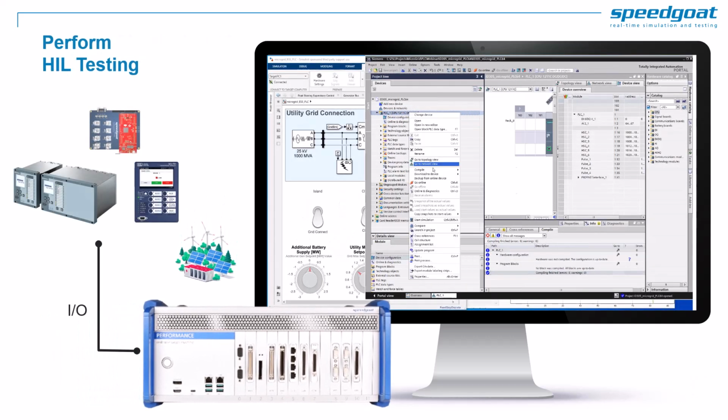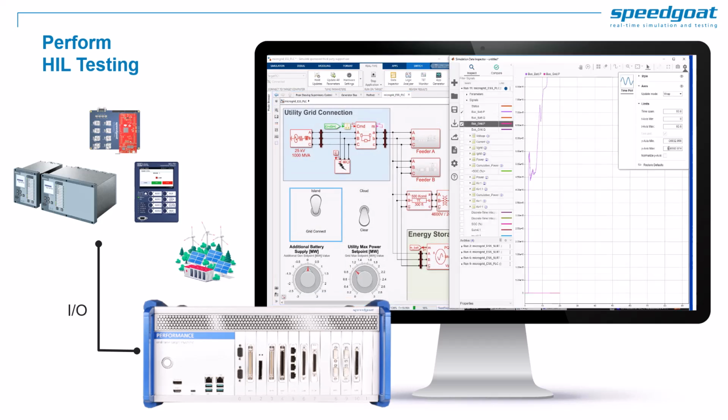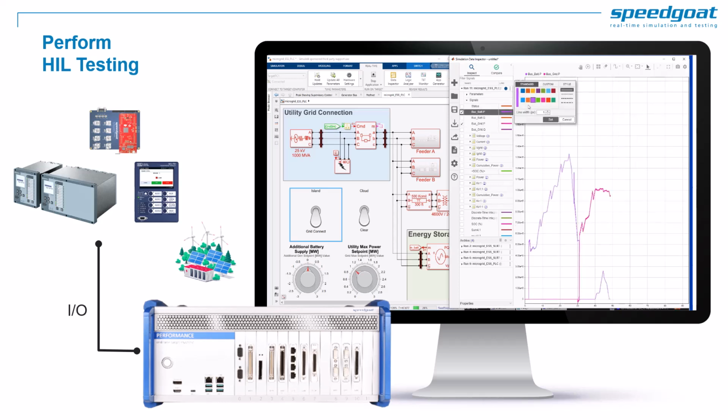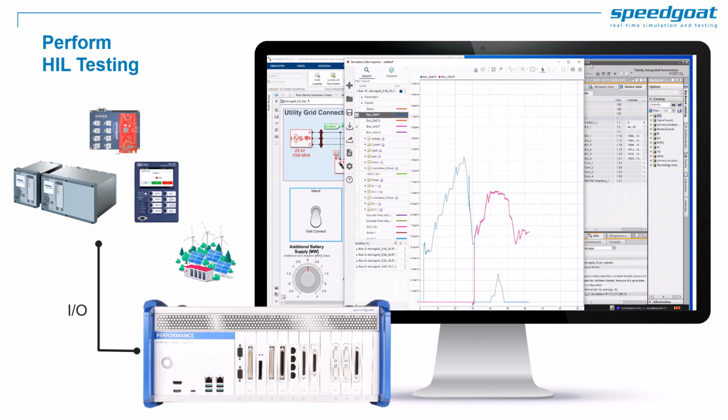Now you have your plant model, which represents your real system. And from the I/O level or communication protocol level, they are running in real time and they behave just like your real plant. The difference is that your plant model is virtual. So when you hook up your controller to the target machine, it's just like you are testing the real system. And you can test them over and over again. And you don't need to be worried about breaking the hardware.